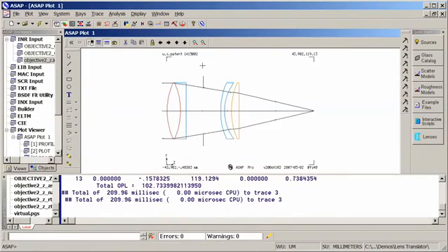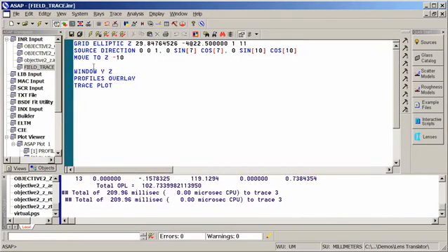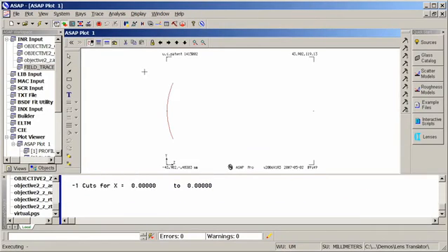And again, here's the system in profile. And one of the things I might want to do is to look at rays from all across the field of view. Since I created these files, I know this system has a 10-degree field of view, so what I'm going to do is trace a set of rays from the on-axis, medial, and the edge of the field. And all I need to do is run this file, and it will trace those rays through that same geometry.